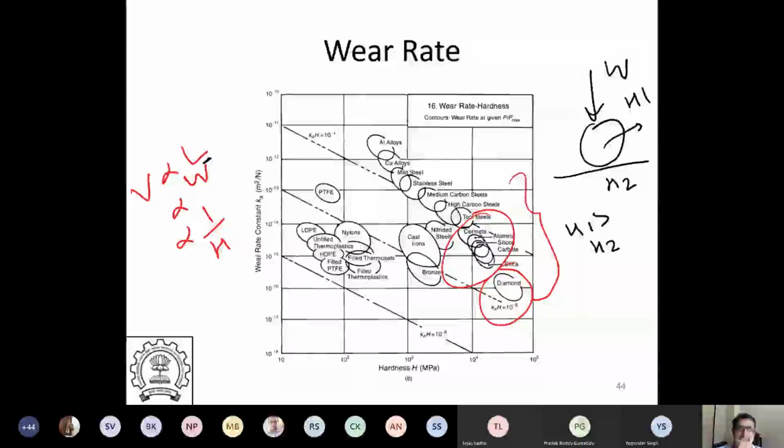Yeah, it's right. There are various mechanisms of wear. Abrasion is one thing. Abrasion is a physical scraping of the material, when there is a physical removal of the material. But most of the wear doesn't happen because of physical wear. One of the key mechanisms, other than abrasion, is something called adhesive wear.